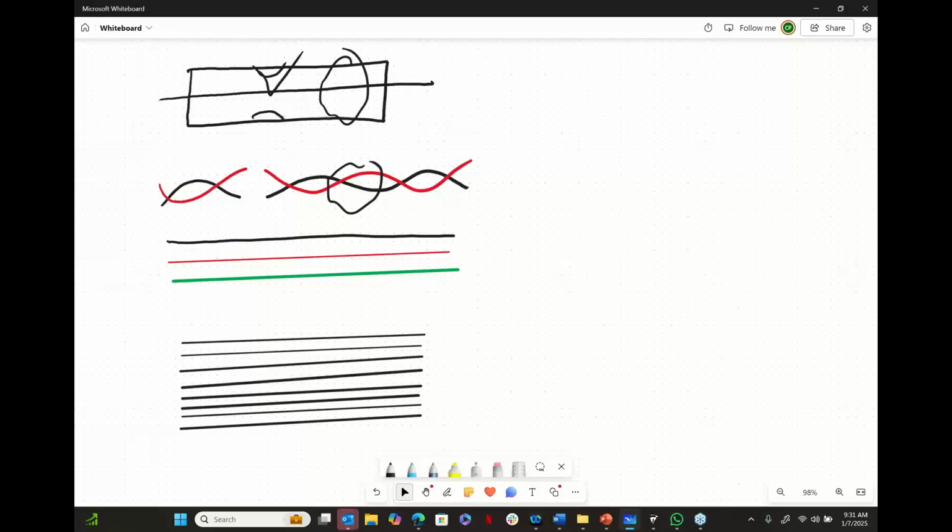Even though the relationship of the conductors may not change to each other, essentially the signal is going down both conductors at the same time. And when water is involved, the signal attempts to jump from one conductor to the other. So that's why a TDR sees that as an impedance mismatch.